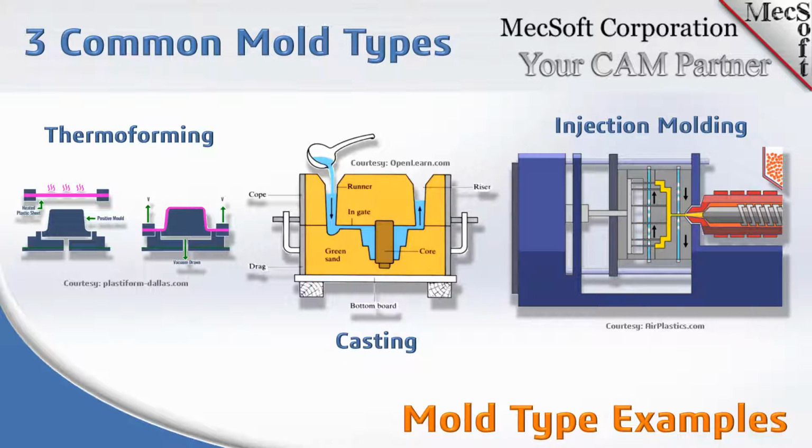It'll eliminate any deflection in the tool, and that's what you want. And on this tool, we show a taper. Obviously, if you have a part that needs draft and your part doesn't have the draft, then you're going to want to use a taper tool in order to machine that draft automatically.